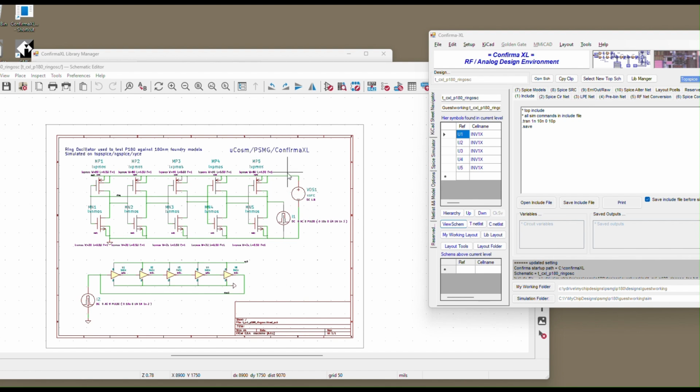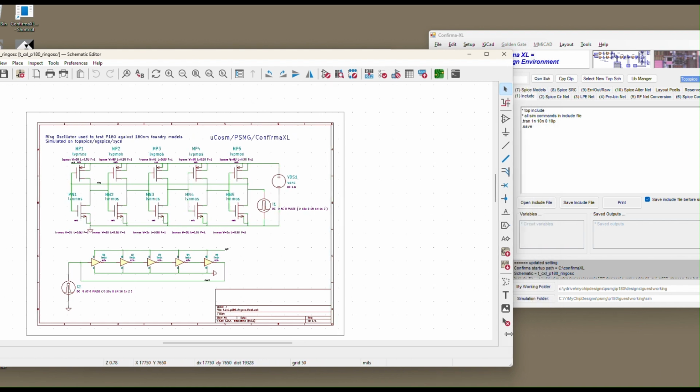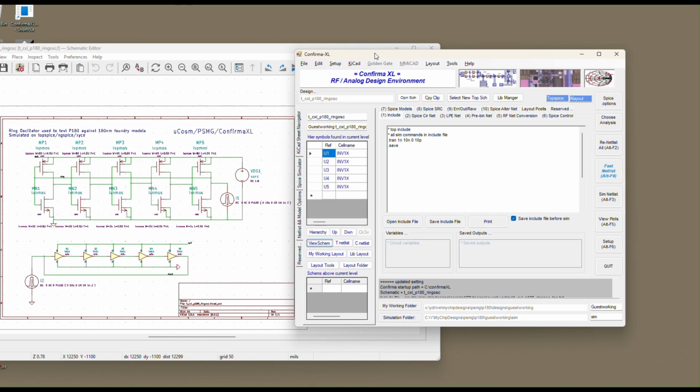This is the power supply. That node is labeled, and that label is shared, so there's a connection via label between these two points. So this guy is also powering this cell as well. These are current pulses, and they're short current pulses. It's just to kickstart the oscillator to get it going faster. Sometimes they'll start up by themselves in the SPICE simulator just due to simulator noise, but it can be helpful to get them to start up quick if you put these current pulses on there. So that's a quick overview of what's on that test bench.